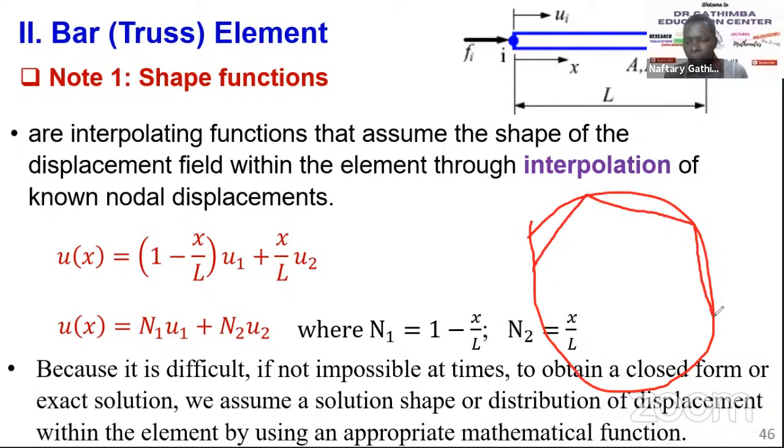We have the different bar elements. So this is the center maybe. If the displacement function we defined was not linear, so maybe it was quadratic, it could go something like this. You can see at this point it's closer to the exact solution than when we have used a straight or a linear bar.